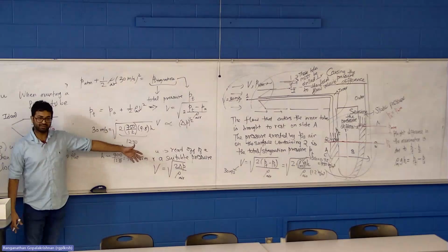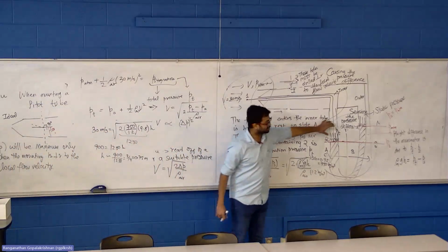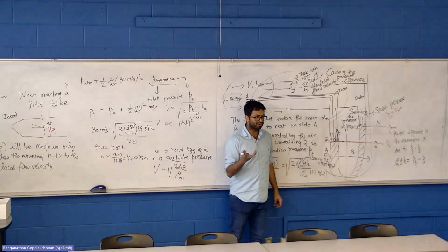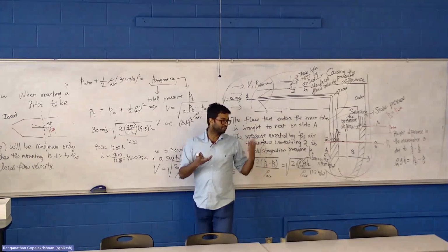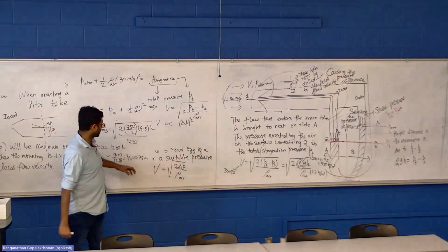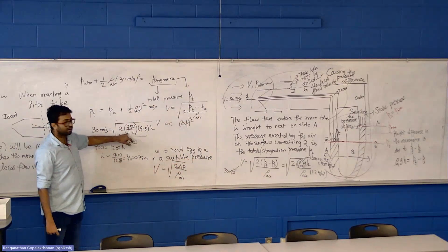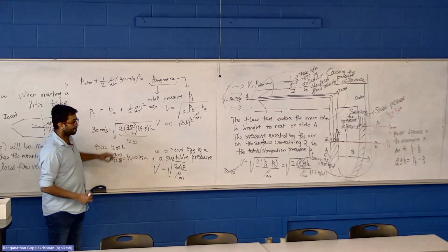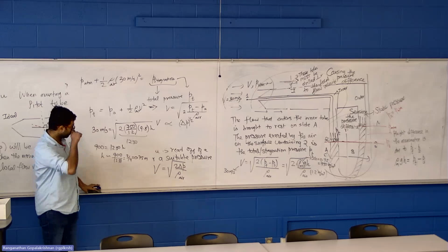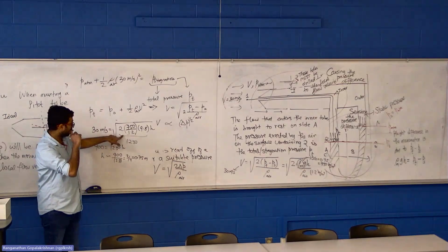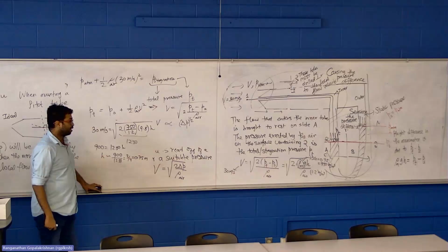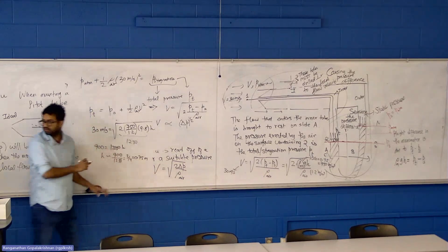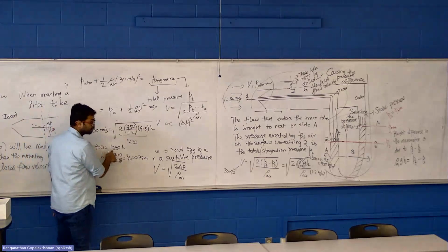Now that does sound like a lot. That's like 75 centimeters. So who wants to have a manometer that's 75 centimeters? But remember the original design of the problem. What was the altitude? 1500 meters. At 1500 meters, do you expect your density to be smaller or larger? Smaller, right? So when I did the calculation inside of the square root, I got 12,250. So I missed something.